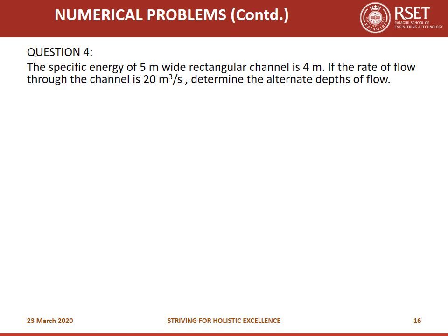How do you find this out? The formula for E is y plus q squared by 2gy squared. Your y is unknown. You end up getting a cubic equation in y, which can be solved. So let's go through the answer.